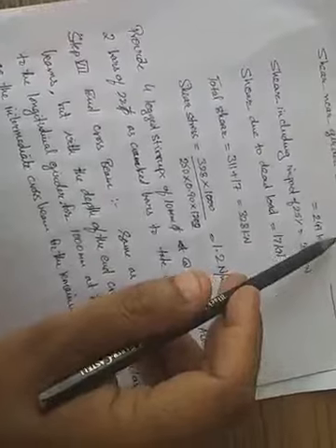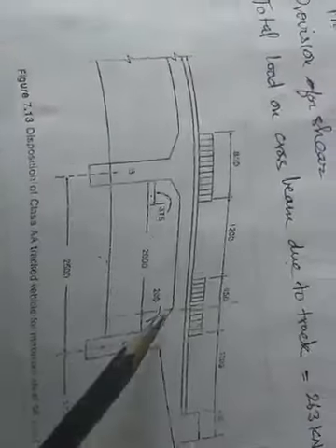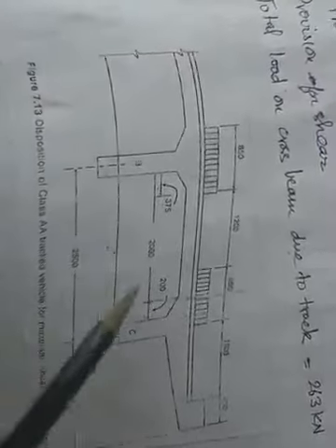So try to understand what I'm going to say. This is not the load, this is rather the shear force. Total load has been considered. Draw a line diagram and you will be able to understand how to calculate the shear force. So this has to be increased by the impact factor, which is 25%. It gives me 311 kilonewton.